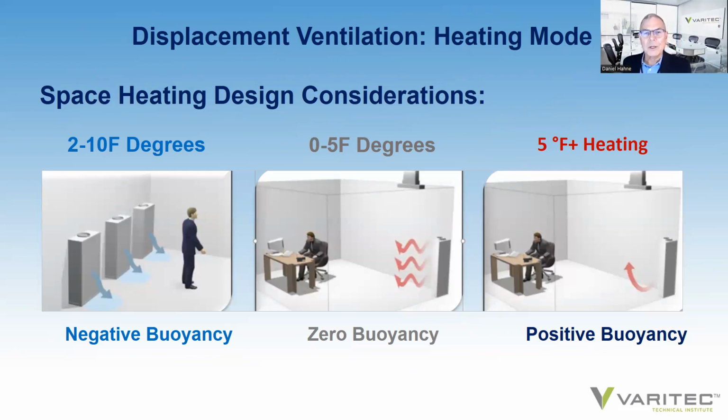The challenge is that if you provide warm air off of a diffuser at low velocity, thermal buoyancy takes over close to the diffuser, and that warm air discharged at low velocity all of a sudden succumbs to convection once released into the space. And that warm air will not mix in the space, but will rise to the upper levels of the room where it will have little to no impact on the thermostat. So you have to be strategic.